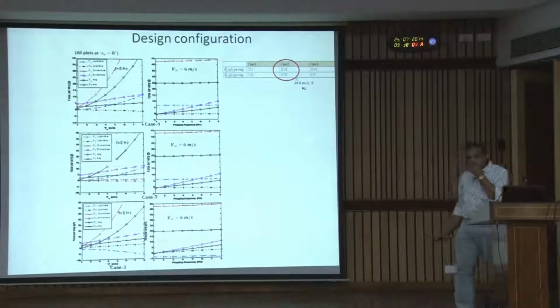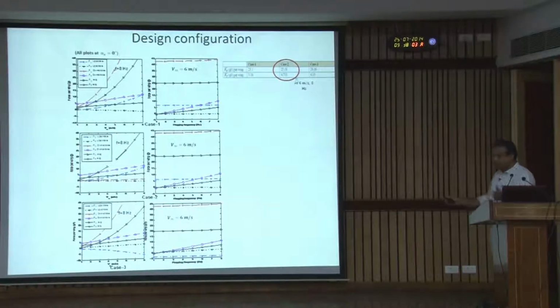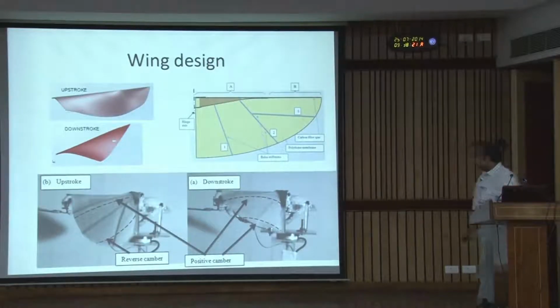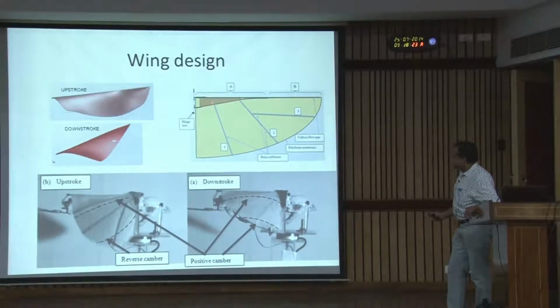The first model that we built, with a 300 to 500 millimetre wingspan, we used this because it is about a 23 gram model, and we thought maybe this estimation would work. You can then do the power estimation and everything. So this is how the wing is designed.